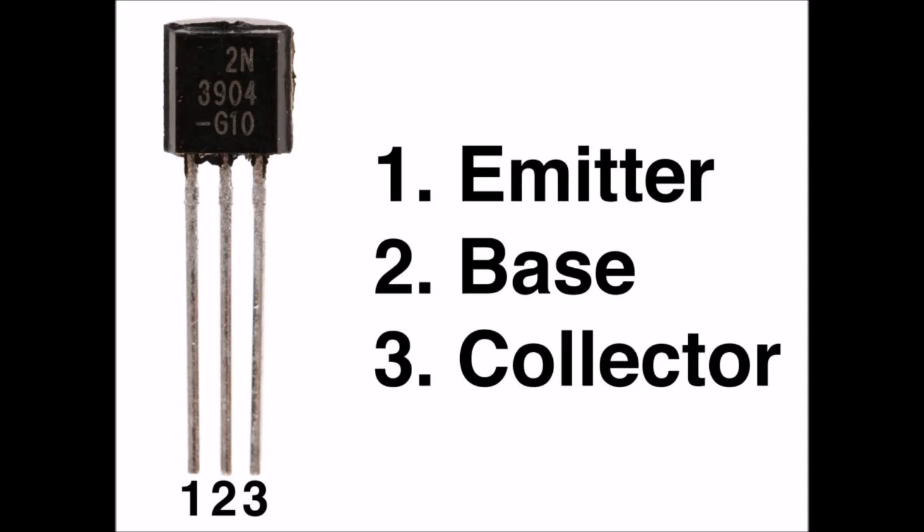We call this ratio the alpha, symbolized as the lowercase Greek letter alpha. Let's abbreviate the words "the difference in" by writing D. Then mathematically we can define this equation. We call this quantity the dynamic current gain of the transistor for the grounded base situation.